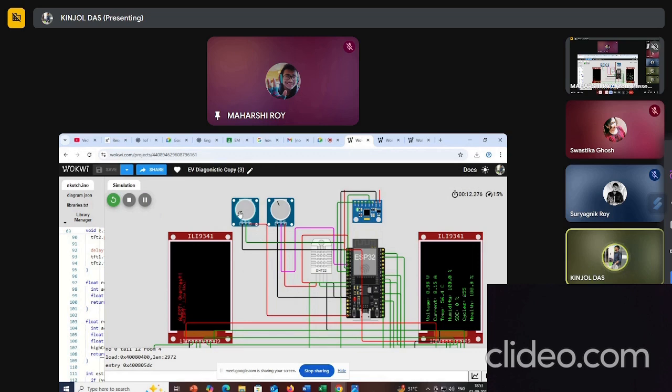So, whenever we change the potentiometer, the battery voltage increases. That means the charging starts. On the right side, you can see the charging starts from 5.2 volts. So it will be detected as a low voltage, as below 12.5 volts is low voltage. So when the battery starts charging, it continues to go up,